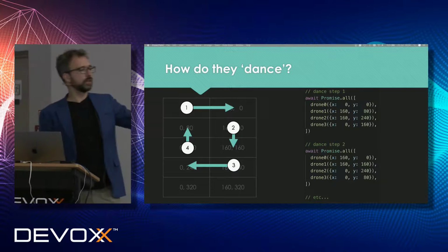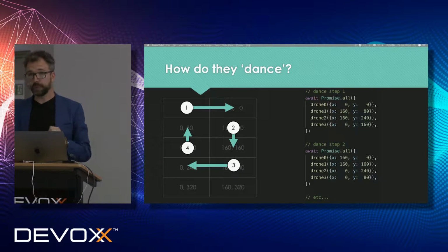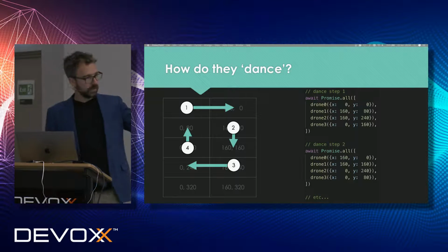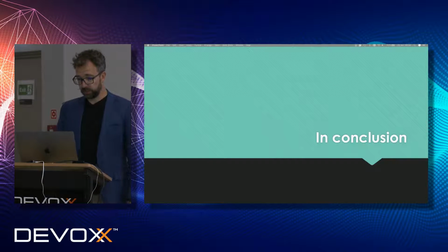As we saw in the beginning of the talk with the one drone that did the takeoff, if you send the command too quickly, then it just ignores it. So that's why it's paramount that you keep inspecting the telemetry to determine where the drone is at that point.